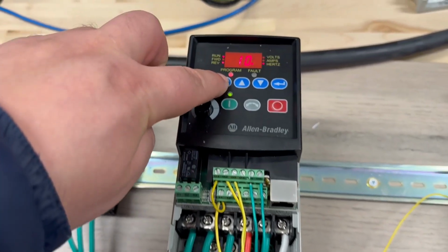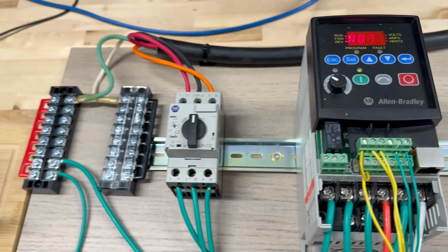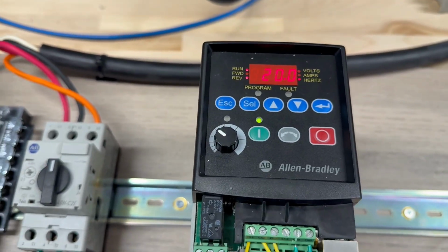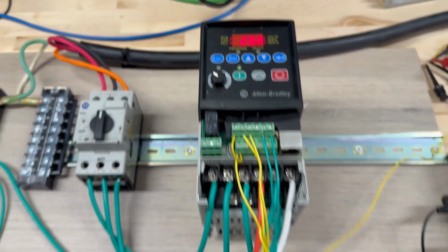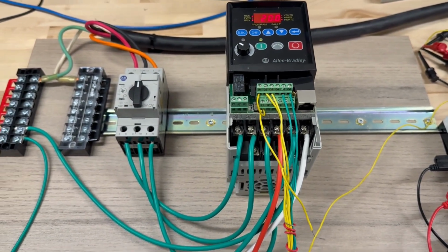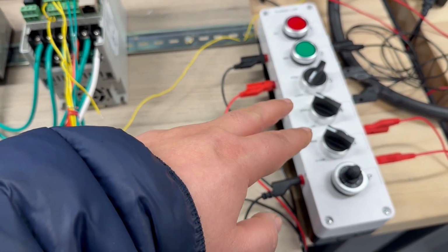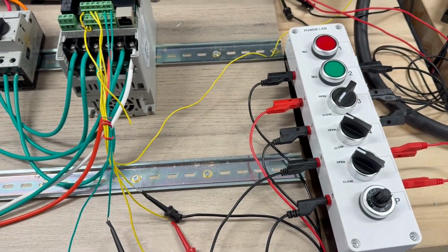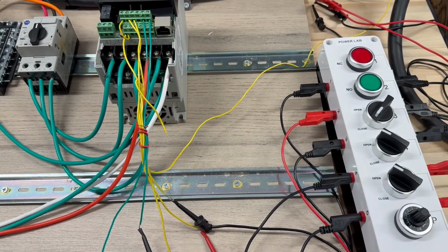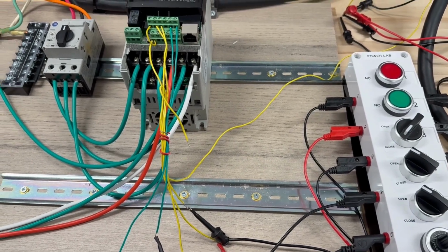And finally A73, if I'm not wrong, the default is 20. It happens whenever both terminals 5 and 6 are 1 with these two switches, so 5 and 6 are connected to the terminal. Whenever both are 0, it gives 0; 1 and 0 gives 5; 0 and 1 gives 10. Both 1 should give us 20, right?